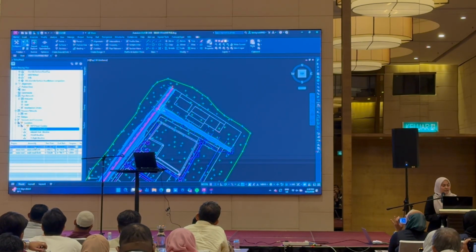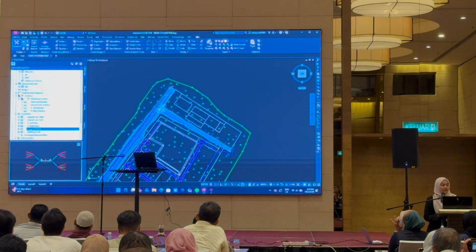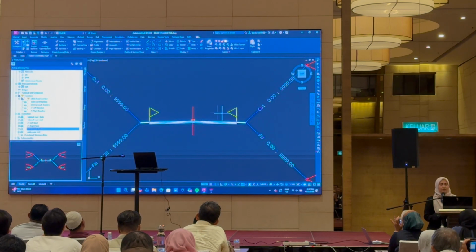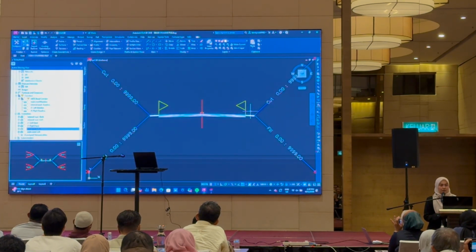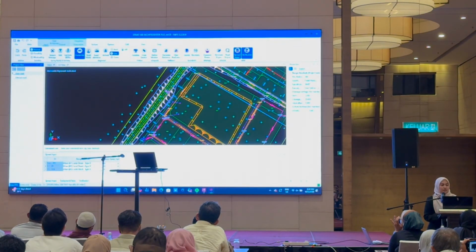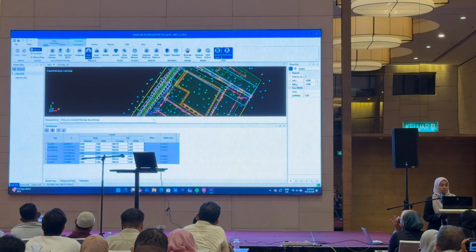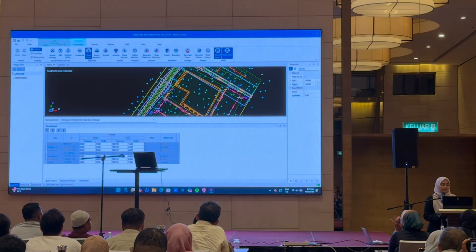So let's say we try to find these assemblies over here. This main road both, and then I would zoom into this particular assembly. As you can see, each side of the road is designed with 2 carriageways and a shoulder. And if we go into MiTS, go to the road width, for the main road, if we go to the spread input, we'll be able to see each of the master string sides. We will have 2 carriageways and a shoulder as well.